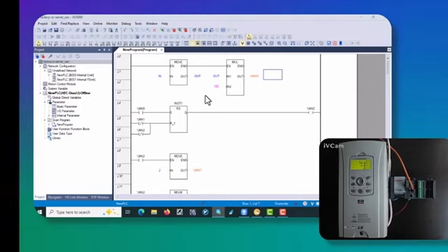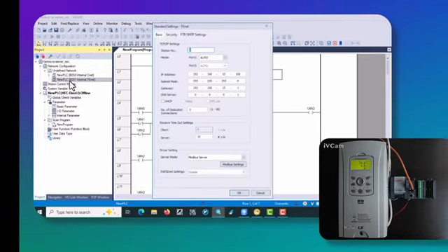the LS model i3. Well, in order to use the Ethernet port or Modbus TCP on the LS PLC, when we open the XG5000 software, we select the PLC type as the U series. In the new PLC Ethernet section, when we click here, a window will open for us.